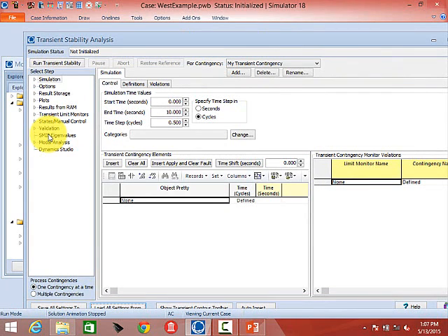As we talked about last time, whenever you run a transient stability simulation, it automatically validates the case. We had allowed you to do that eigenvalue analysis without doing that, and we decided this really doesn't make sense, because they can't run the case without doing the validation. So why are we letting them do single machine infinite bus without doing it? So now you have to validate it.